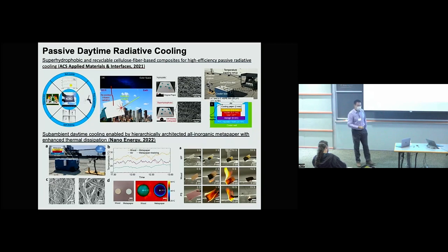And then we received quite a bit of interest from industry. People are asking me whether we can commercialize this idea, and definitely we can do that. We received a lot of questions from end users. One comment that we received last year is about outdoor applications. This material already has really nice optical properties, just like the one I just showed you. It has a high reflectivity in the solar wavelength range, and also high emissivity in the first transmission window of the Earth.